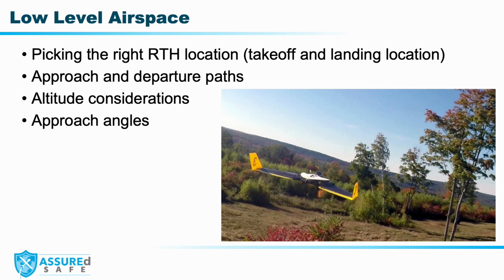Most systems use the altitude above launch location, which means in varying terrain this can become a safety hazard if you do not thoroughly vet the height of obstacles and terrain above the launch altitude.